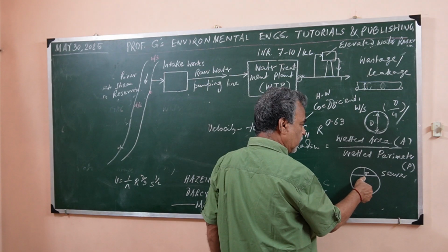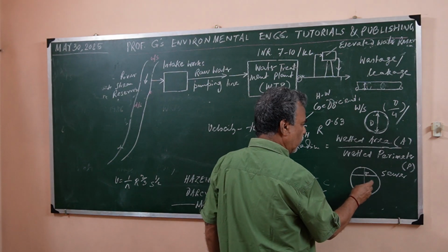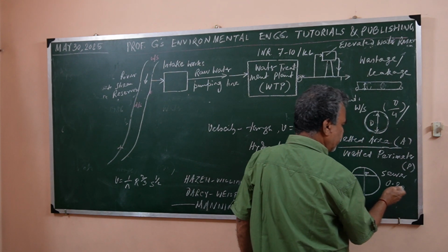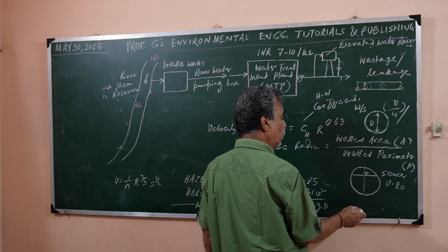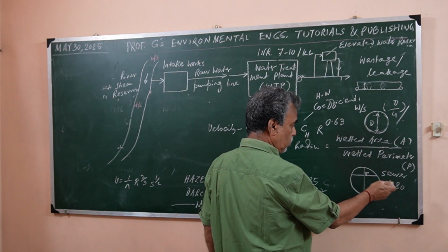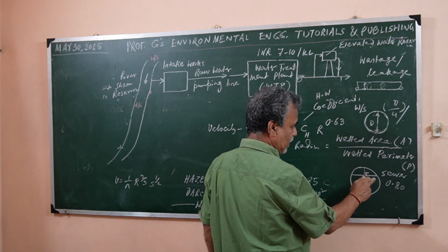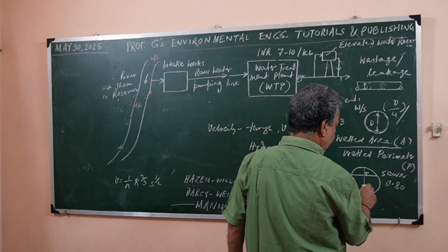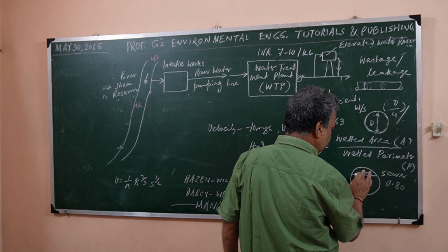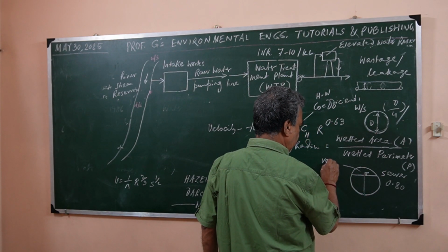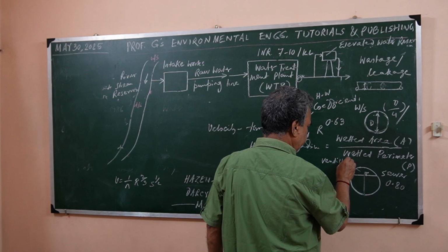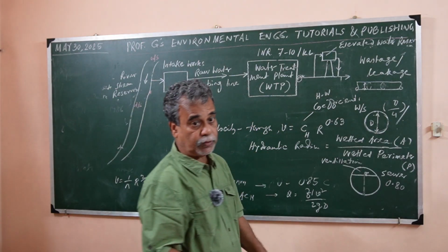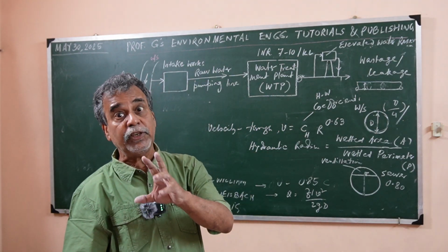It is always deliberately kept, say usually 0.8 or so, depending on the requirements and your available flow. So that way this will be decided. In the sewer line, this part is for ventilation, right? Because otherwise the fouling will be there, because this carries wastewater, remember, sewage, which is decomposable.